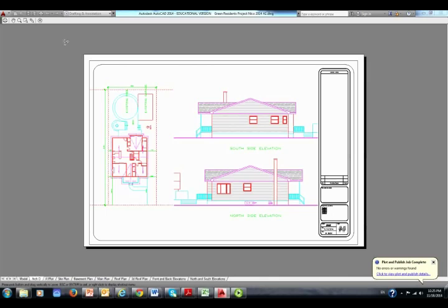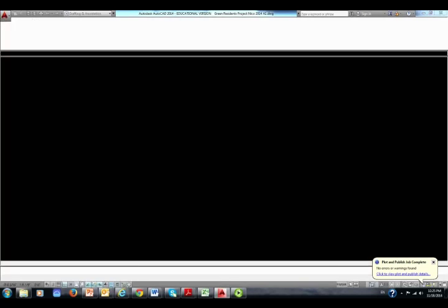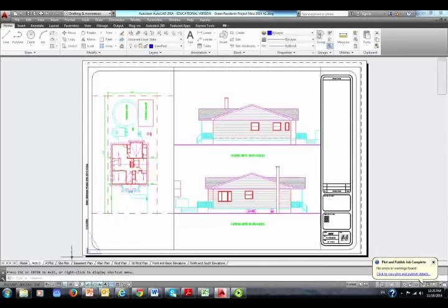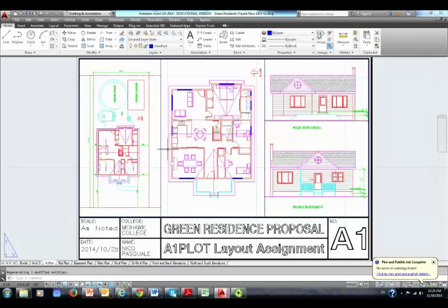It must be. The plot preview for my ArchD template comes up color, but my technique for not showing viewports has worked. For the A1 plot, I have gone and compared all of the settings for Page Setup Manager, plotters, printers, monochrome.